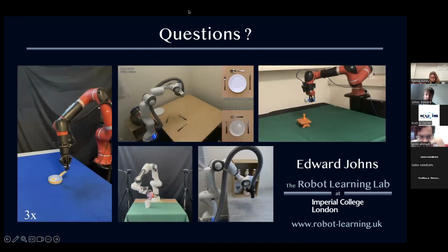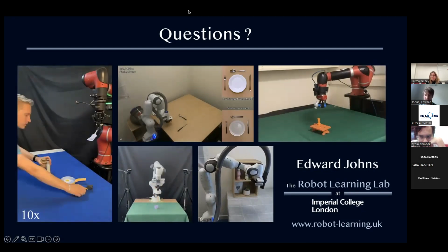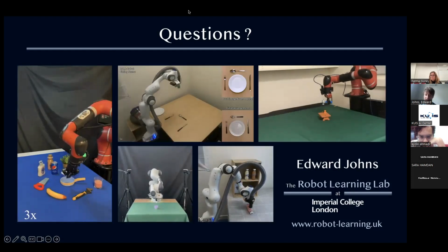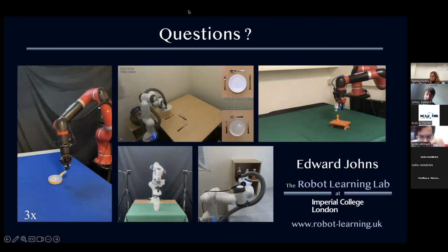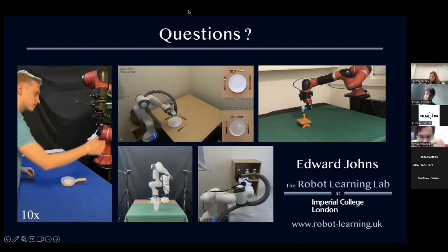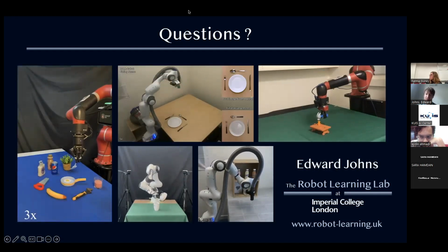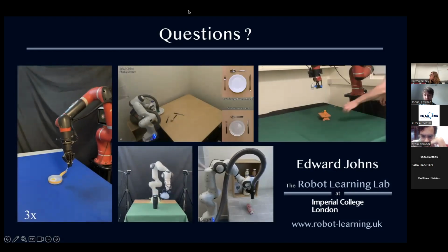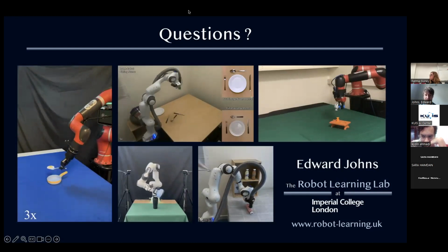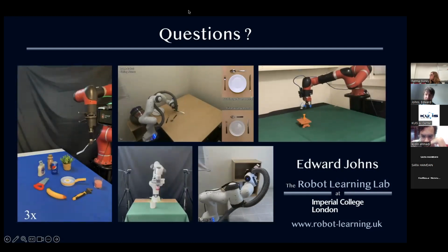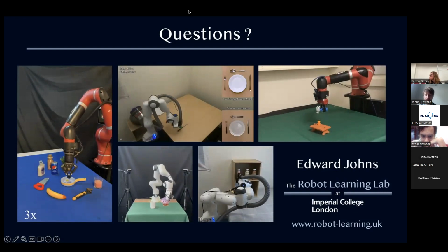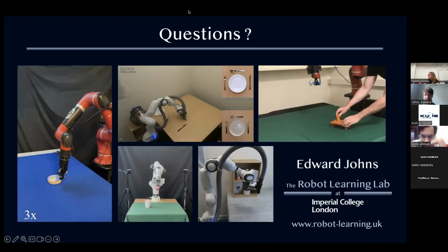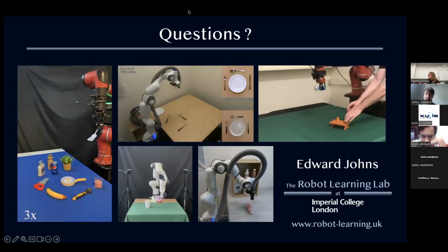The other is that for the actual interaction with the object, once the robot is aligned appropriately with the object, it can just replay that demonstration, and the action part isn't actually being predicted at all. It is simply remembering what the human did. So in the example on the left, where the robot is scooping up the egg, there's quite a complex trajectory, getting that spatula underneath the egg and lifting it up. If you were to train this through regular behavioral cloning with something like a transformer, you might need hundreds of demonstrations to get this behavior. Whereas if you just focus on the alignment part and then replay the demonstration, this is much more efficient.